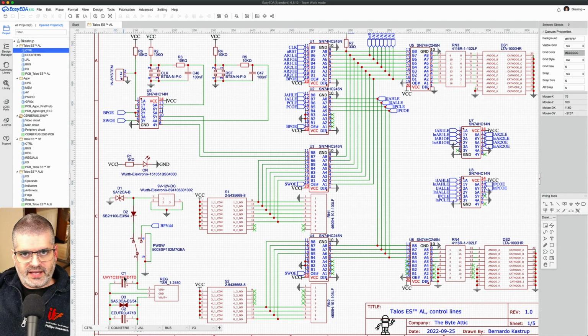Keep in mind that the diameter should be 5 millimeters, and look at the other characteristics of this capacitor that I'm recommending, just to make sure that the footprint will be okay. Although even if the footprint is not the same, you can always bend the legs a little bit. But remember to please do it, because the capacitor you have installed there, in the position of C1, will not last. Apologies for that.